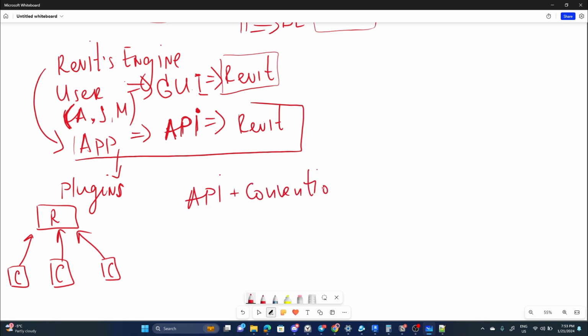like where we need to put some files and what that file should look like, and this is like an add-in file. So we just learned that we've got to tell Revit somehow how to get our command. That's the main question it answers: how to get what we have built.